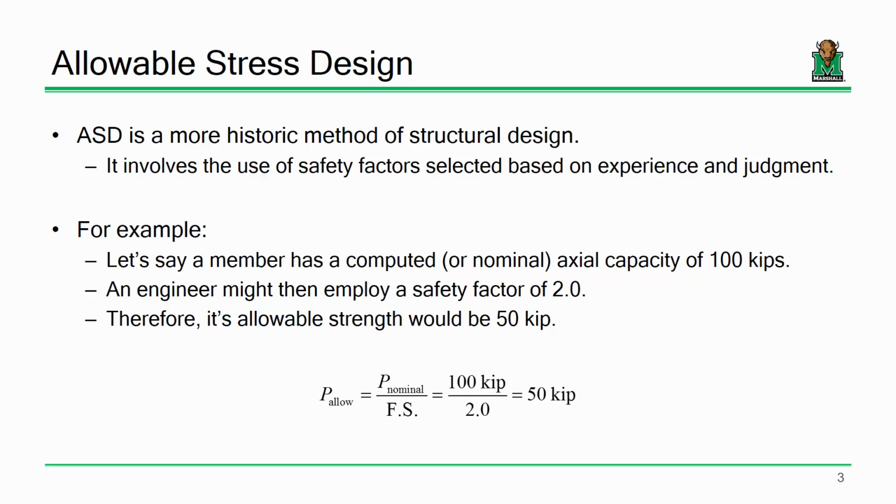Okay, so allowable stress is a pretty basic concept. I go down to the lab, and I take this table with me, and I put it under an actuator because I like breaking things. My general philosophy is any day with controlled demolition is a good day. So I put it under an actuator and I start pressing down on this thing until, boom, it breaks. Let's say I do the math and I find that this table breaks at 800 pounds. So I know that this table will physically fail at a load of 800 pounds.